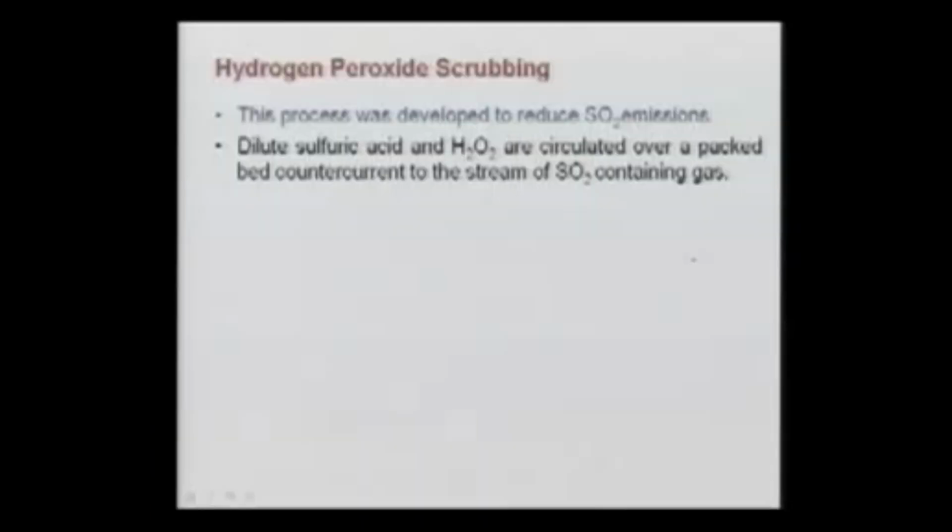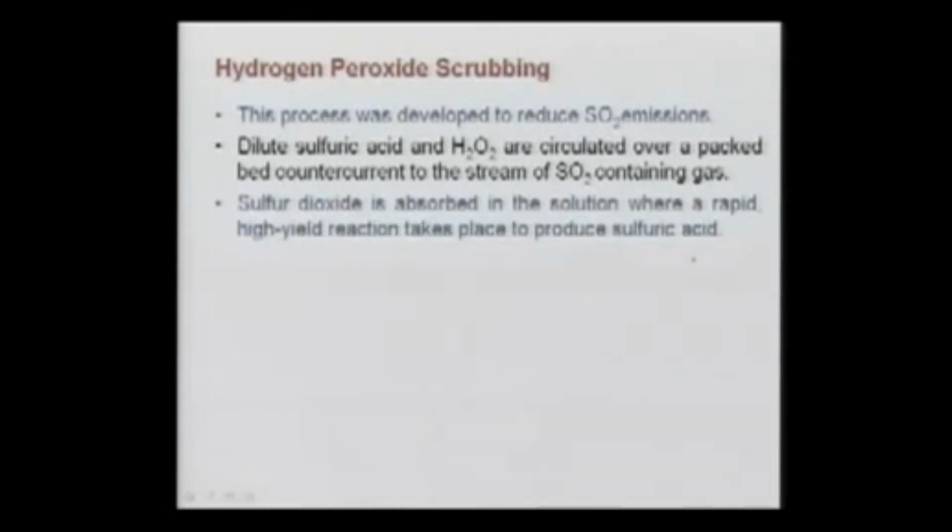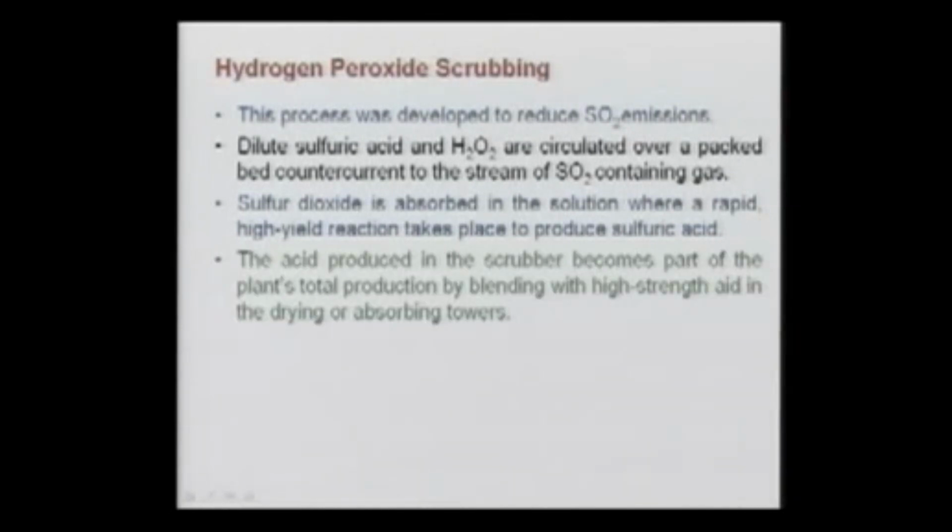But still, if you want a very, very clean stack and you don't want any SO2 emission to go out, the technology has been developed by the oxidation of the sulfur dioxide with H2O2, and what you can see here, this process was developed to reduce the SO2 emissions.